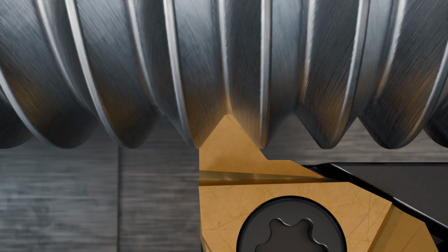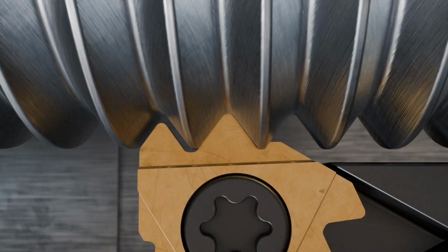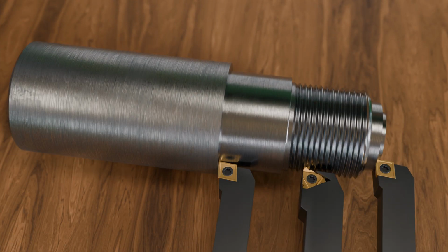For both full-profile and partial-profile thread inserts, many passes are usually required until the final thread depth is reached. Using so-called multi-tooth inserts can significantly reduce the number of passes, as a smaller tooth pre-cuts the thread. This allows for deeper cuts per pass. However, using multi-tooth thread inserts requires very powerful lathes. Next, we will briefly cover additional turning methods.